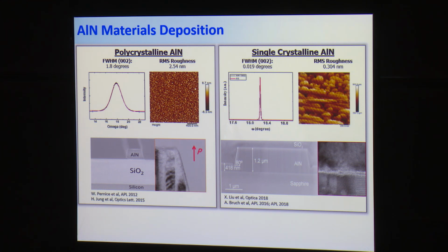These are really an advance of the solid-state lighting industry, which gives you this film that can be grown directly on sapphire. For most of your LEDs, sapphire is cheap, right? So they grow on sapphire. Gallium nitride grown on sapphire produces very efficient LEDs. So you can make large wafers, like 2 to 3 inch wafers, and make many of them. Those are lattice matched. In the TEM image, you can see the atoms, and the X-ray rocking curve gives a very narrow linewidth. The surface roughness also goes down by a factor of 10. It's a very smooth structure.